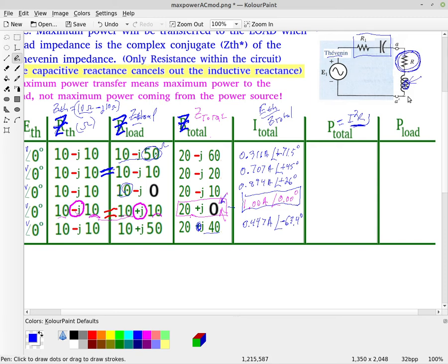So we're not worried about the voltage drop across the inductor, all right? And that's where this equation comes in very nice. I squared R gives us true power being used. And so its total power includes the power in this Thevenin resistance and in the load resistance, but it doesn't include power being stored within those inductors and that sort of thing.